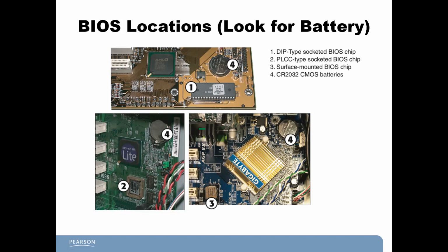Commonplace, where sometimes we see that CMOS batteries go bad, is probably when your system is not able to keep track of the time. That means your time and the date continuously keeps on changing. That's where you know that your computer's CMOS battery has gone bad and needs a replacement.